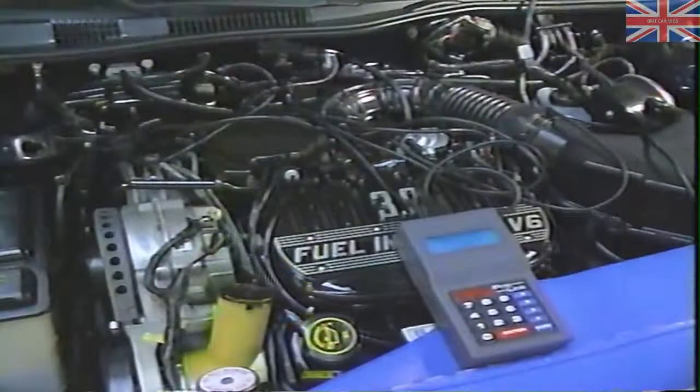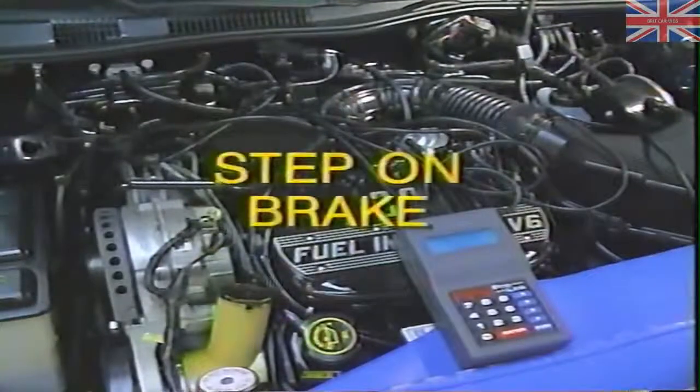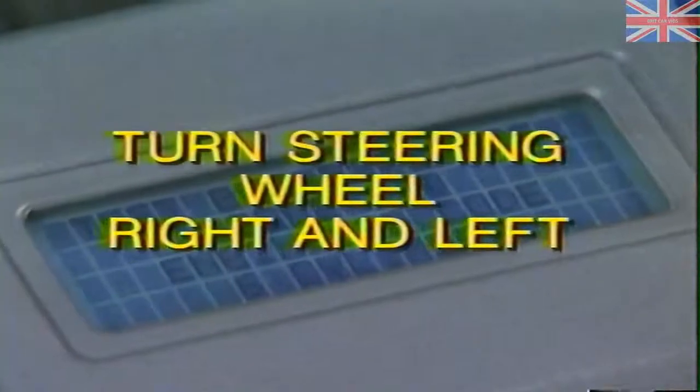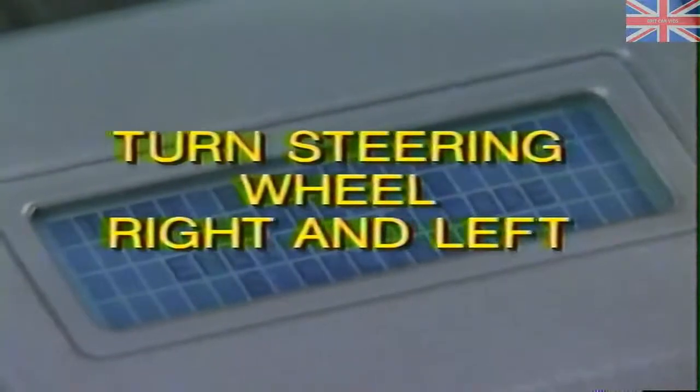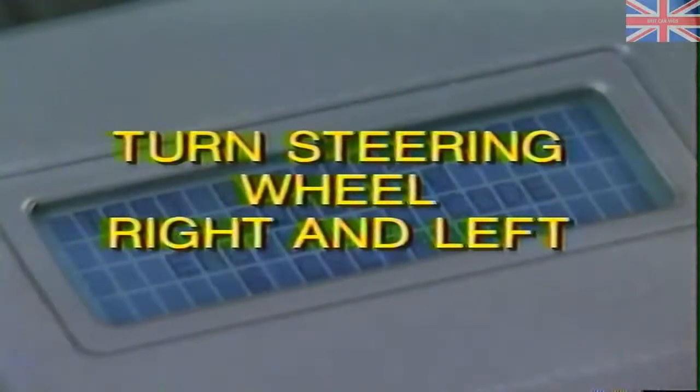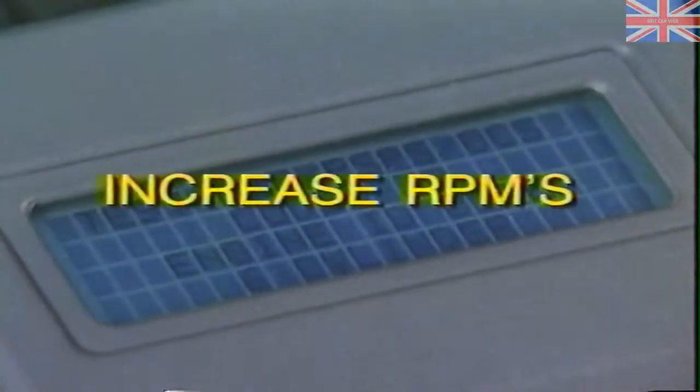Immediately after we receive the ID codes, we should depress the brake pedal. This will allow the engine control computer to check the brake switch for functioning. Next, turn the steering wheel approximately 3/4 to a 1/2 turn and release it. This will check the power steering switch. Next, quickly stab the throttle for a wide-open throttle position.